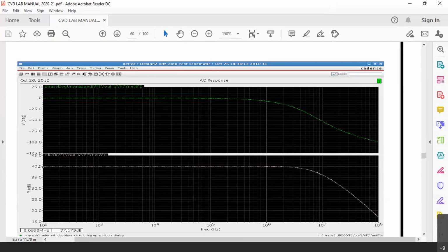This is now a direct coupled amplifier, because at the input there are no coupling capacitances connected, unlike BJT. In BJT, we need coupling capacitances. But in MOSFETs, we don't require coupling capacitances, because they already have capacitances as gate capacitances. And there is no gate current at all.